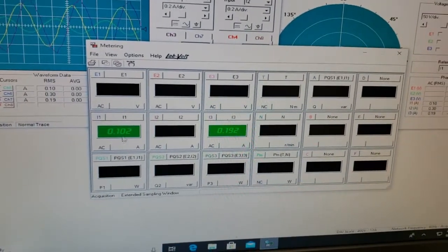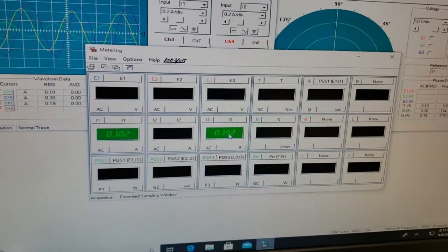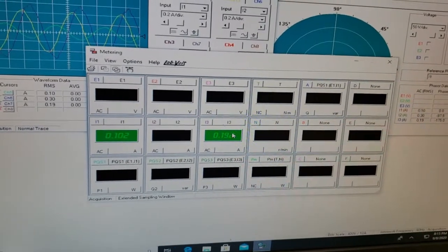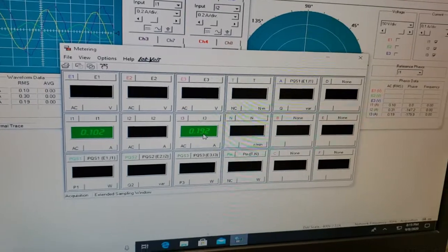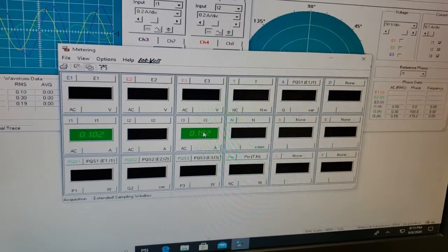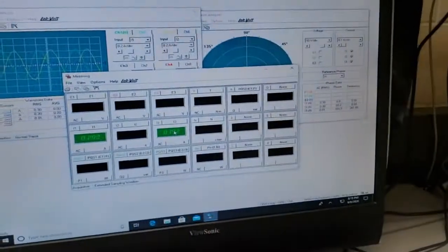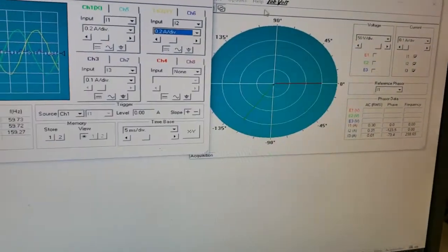First of all, it's taking a whole lot less current. And look at the neutral line. Now the neutral line is really taking a lot more current. And that's what happens when the load becomes unbalanced. When your three-phase Y-configured load becomes unbalanced, the neutral line starts to take a whole lot more current. Okay? And I also want to show you actually one more thing. So I'm going to return that back to being a balanced three-phase load. I actually want to show you the waveforms.